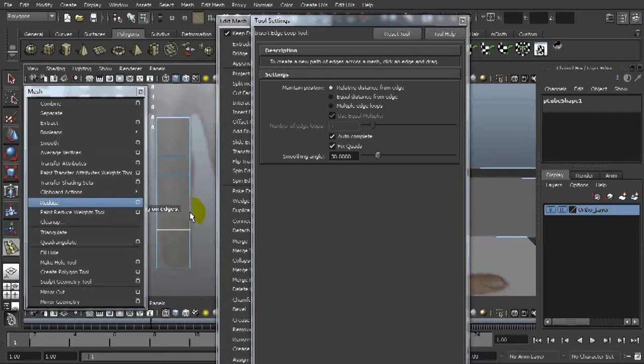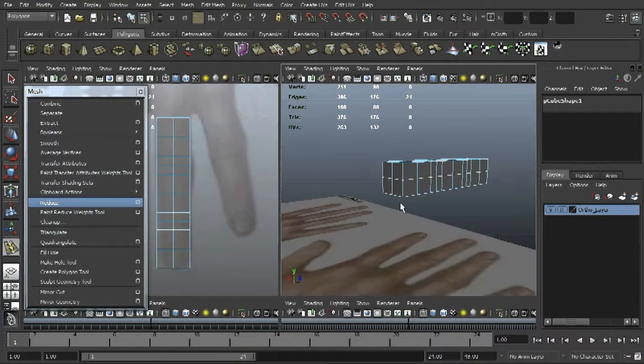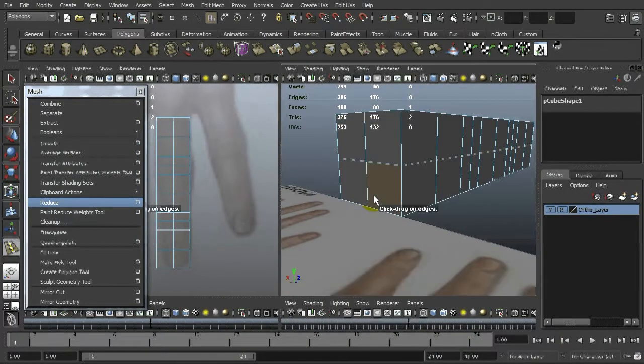When you're inserting edge loops, you can toggle your options. The little box always gives you options for whichever tool you're selecting, telling it how exactly you want it to insert edge loops. I'm just going to use something basic and simple, equal distance. Sometimes you might want equal distances, sometimes you might want something else. It's all situational, so keep that in mind whenever you're creating your edges.